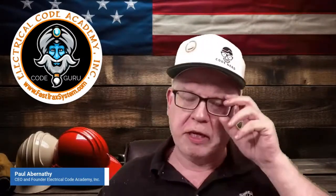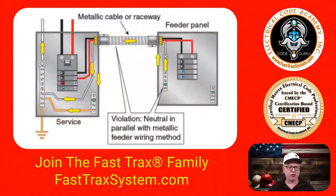All right, so here's the illustration that we were talking about. So here you have your service conductors coming in, all right? And here's your main service disconnect. Here's your grounded neutral conductor coming from the utility, okay? It's coming in, and you see this bus. Now, just to let you know, see this conductor right here? This is a main bonding jumper.